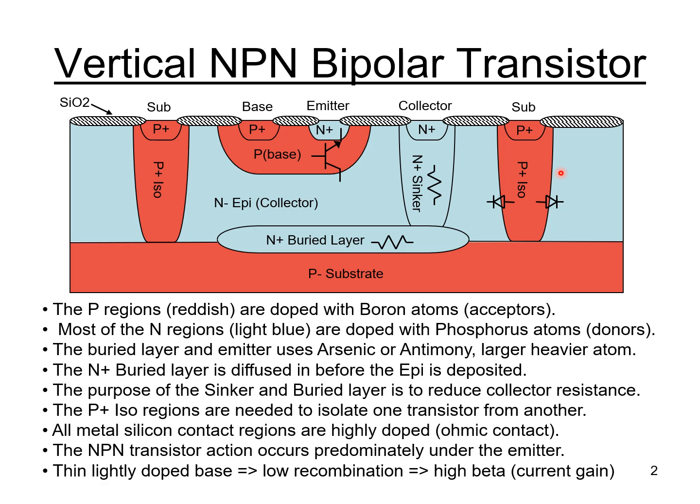And we've shown a couple of diodes there, and those diodes act as electrical isolation between the one collector and the other collector. Now, it's not an insulator. This is called junction isolation, and what we're doing is we're using reverse bias diodes to isolate one region from an adjacent region, as opposed to trying to put an insulator in there.